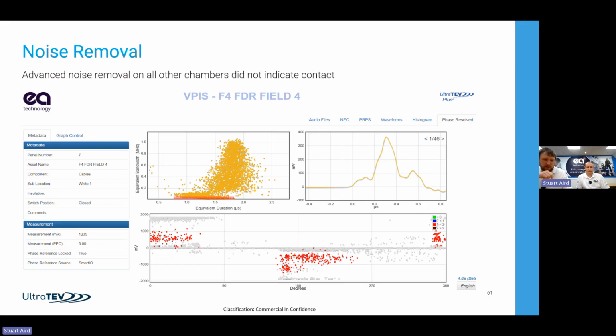Root cause for this? Dead simple. Bolts are different sizes, different lengths. On one phase it was tight, and that had a slightly shorter bolt than the other two. The other two were sticking out a bit too far. So from day one, a build error, the wrong component being used, and you've now got something that would have led to failure had it not been detected. So there's a case study of how the techniques and the analysis are starting to give you the confidence in these decisions. And being blunt, that's what we're there for.